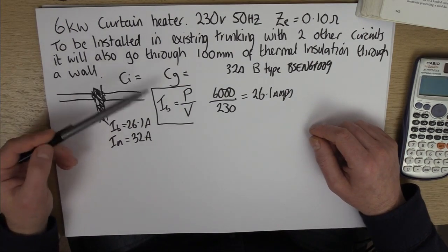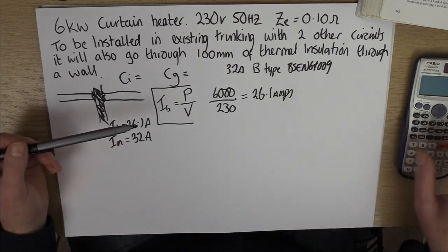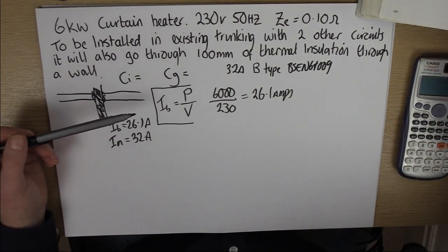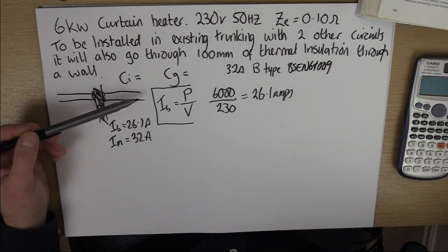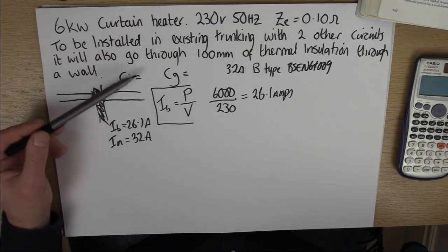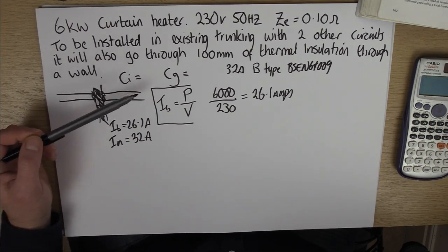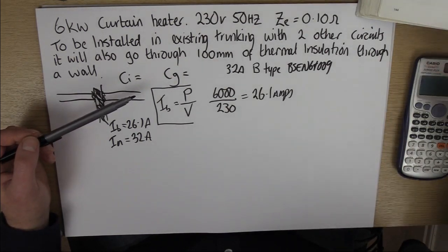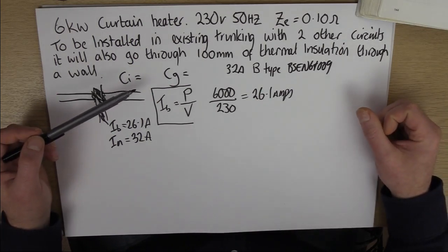Now we're going to have an insulation factor and a grouping factor. Now I'm just going to try and keep that quite simple really. So we're going to use the factors in, where is it? Now that's not near the other grouping factors in the regs book. It's in 523. Hold on. 523.9. There we go. Got there in the end. I'm telling you, the reg stuff, it's in your head 1 minute and then it falls out. Anyway, table 52.2 is what I'm after.